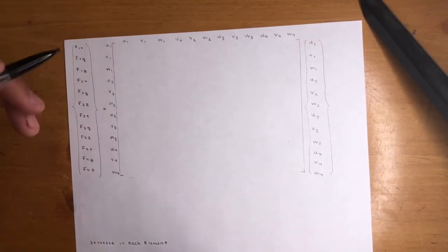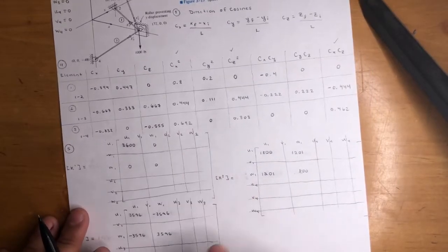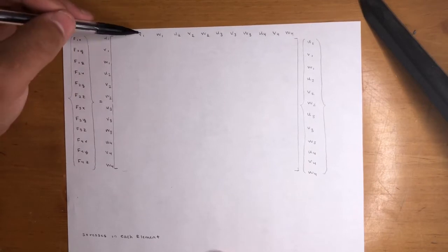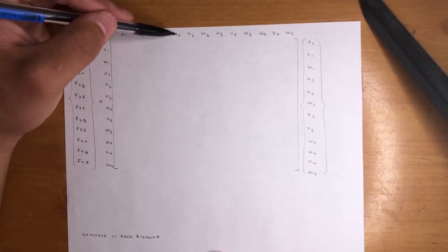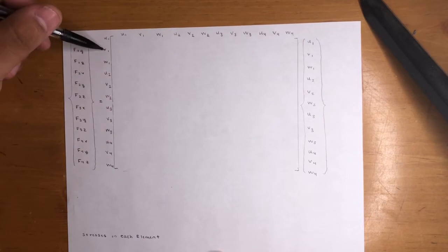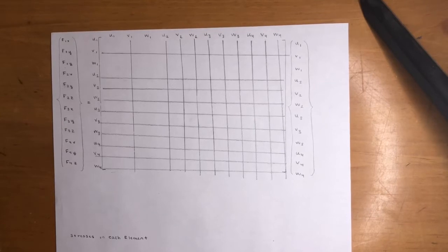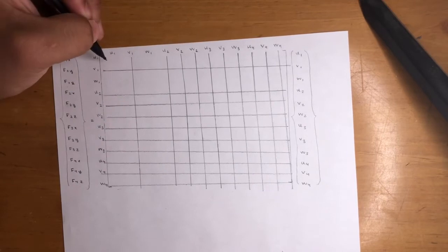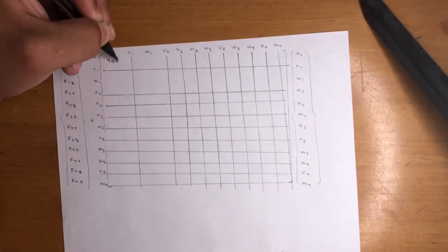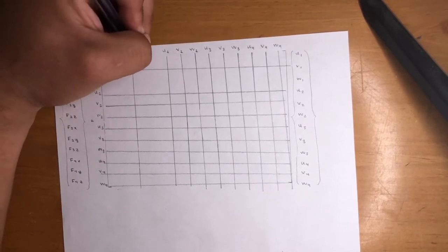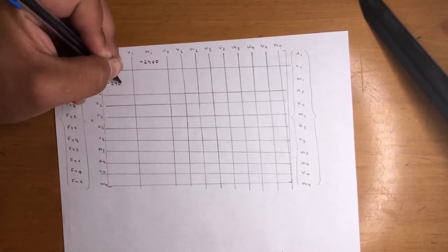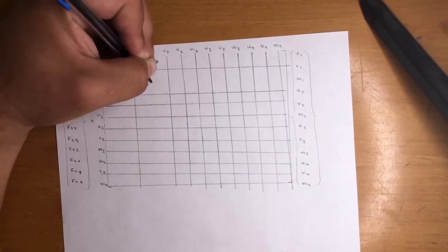So remember, we canceled just the way we did here, apply the boundary conditions. We're gonna go ahead and do that here as well. So let me go ahead and do that. I'm just gonna cancel V1 and everything from U2 forward because they're all 0. And same thing here, V1 and U2 all the way down. All right, so I did just that, right? Excuse the lines, they are not the best, but if you add all the U1U1s, remember, you get 9,000 up here. And I did some rounding on the other numbers. It shouldn't mess us up. It's not that big of a deal, but these are the numbers you get if you do the math.